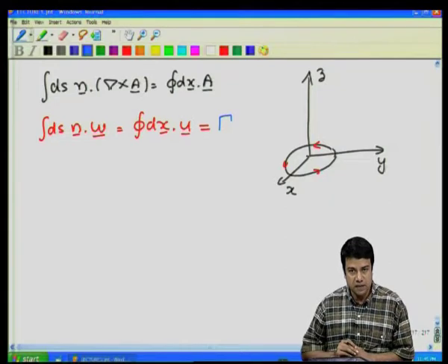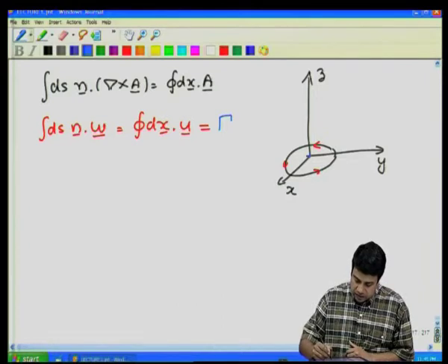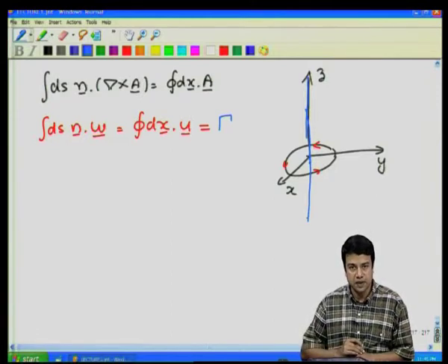The answer to the paradox is as follows. The vorticity itself is a delta function along the origin here, along the z axis. So, for this two-dimensional flow, one can consider the vorticity in 2 dimensions to be a delta function right at the origin. That means that there is a vorticity at the origin itself, but there is no vorticity anywhere else in the flow.